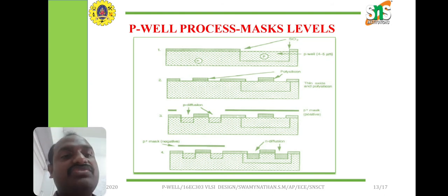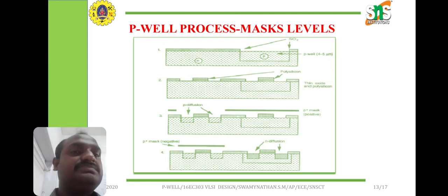Then you can make the N diffusion, because I already told you the keyword: same diffusion, different substrate. So if the substrate is P, then N diffusion. If the substrate is N, then P diffusion. That is the main concept you need to remember.